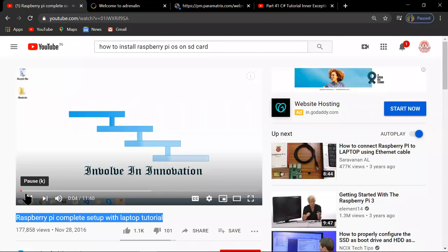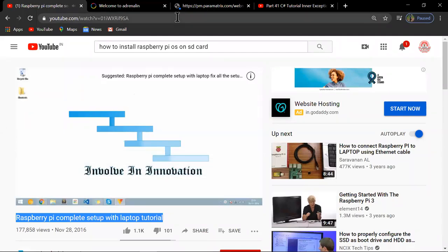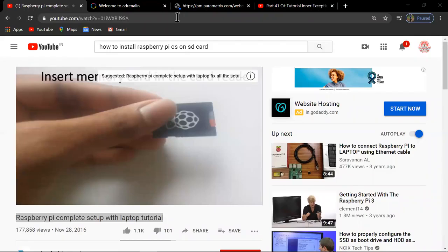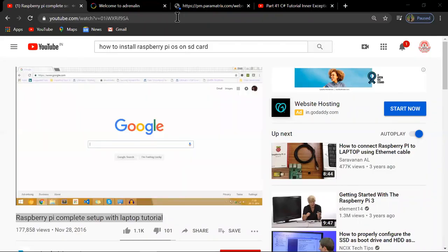Raspberry Pi. First take the memory card in which we need to load the Raspbian OS and mount it in the card reader and insert it in the card reader slot in the laptop. First format your memory card. For that we need to use SD card formatter. We can use operating system provided formatting utilities, but that may result in less optimal performance.